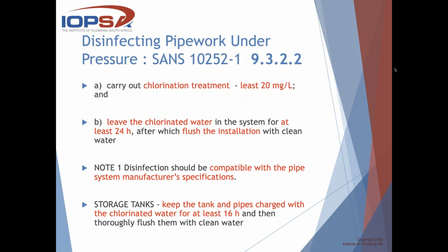If they say don't use anything like chlorine, or if they've got something specific, then use that product. And the same would be for plastic pipes as well, because now remember, you want it to be disinfected because of Legionnaires as well. So you do that the same for plastic storage tanks. Keep the tank and pipes charged with the chlorinated water for at least 16 hours, and then thoroughly flush them with clean water.